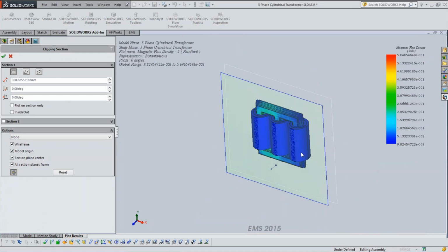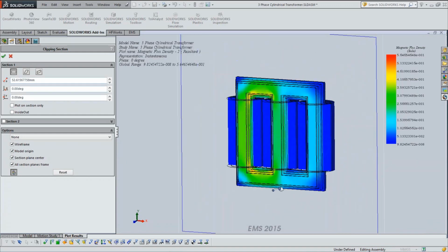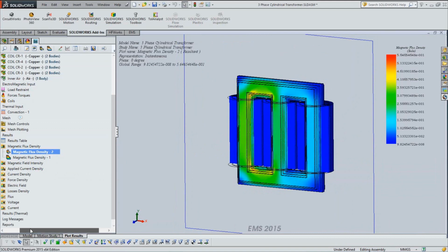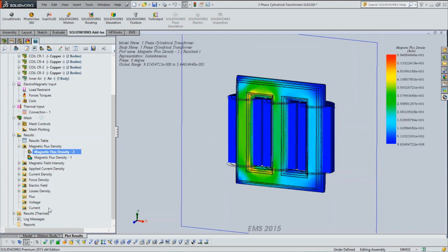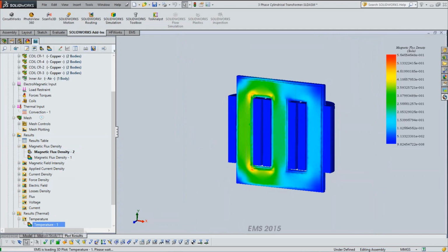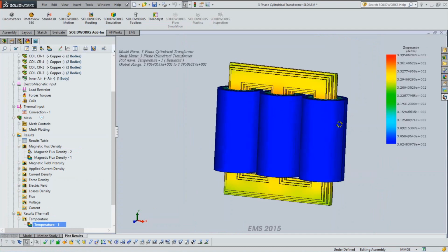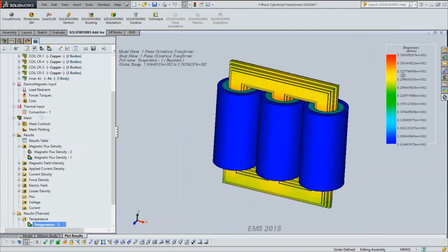It might be a little bit slow coming through the internet, the dynamic movement, but you can see that. So you can have a section plot that will help you to see inside the model. And one can also now, as we saw, the thermal results become very important. I can now take a look at my steady state temperature distribution inside the transformer. So this is my distribution of temperature inside my core and in the transformer.